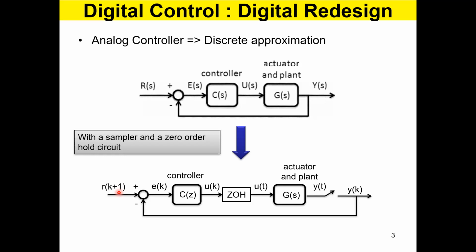Now, the last thing I want to tell along these lines is that you are not going to develop the difference equation directly from the plant. What you're going to do is to develop the difference equation of the controller using the continuous time controller, which is already available here. The controller is available.